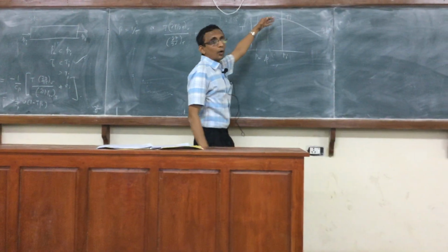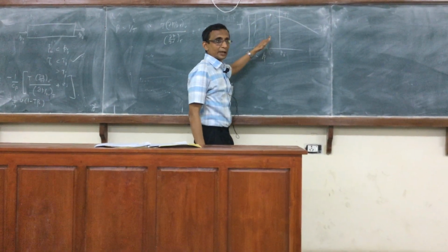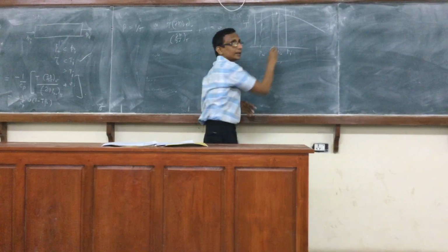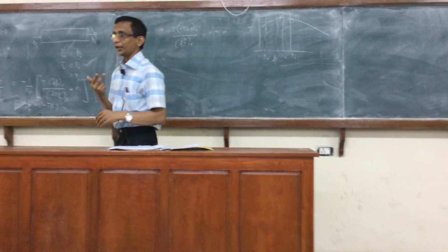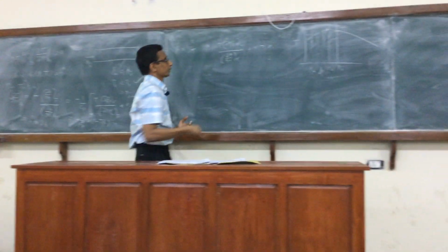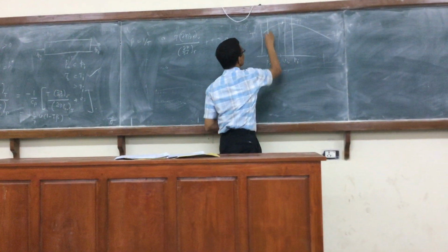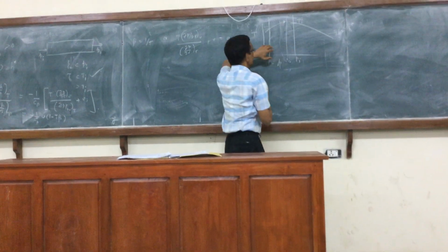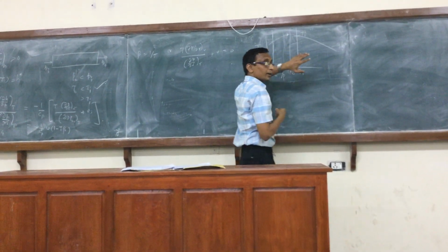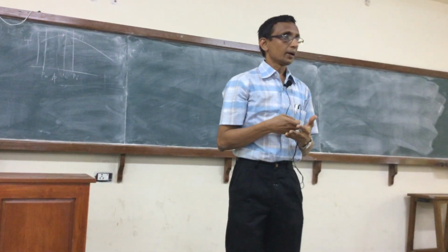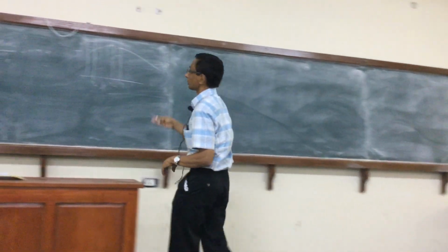Now, depending on the degree of expansion, for instance, if the degree of expansion is such that P naught is only here, you can even have a heating of the fluid. So we have to make sure that the degree of expansion is such that, if you want to cool, you cannot just blindly feed the fluid in without paying any attention to the degree of expansion.